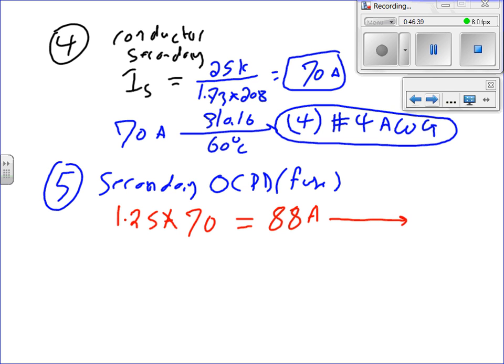Then you take this one to, not 310.16, Chad. You're going to take this one to 240.6. And if it's not a standard, can I go up? Yep. Is it a standard? No. So where do I go? To 90 amp. 90 amp.